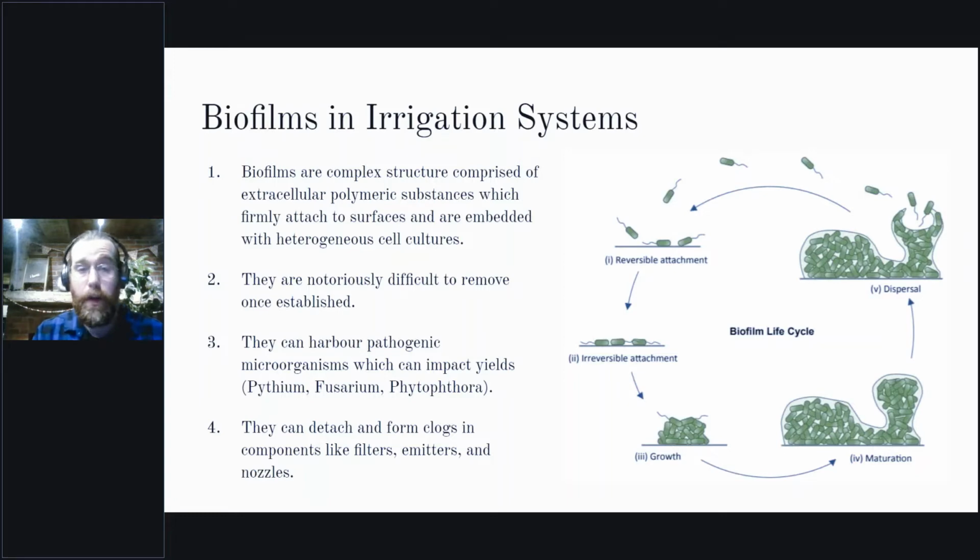They're notoriously difficult to remove once they're established, and they can harbor pathogenic microorganisms like Pythium, Fusarium, Phytophthora. They can also detach and form clogs, so-called sloughing, in components like filters, emitters, nozzles, and anybody who's experienced aggressive biofilm knows what a challenge it can be.